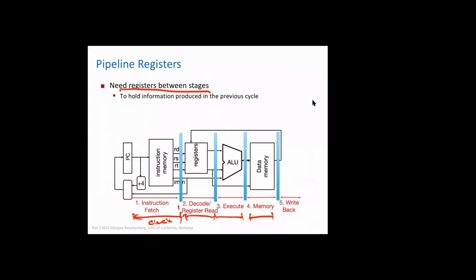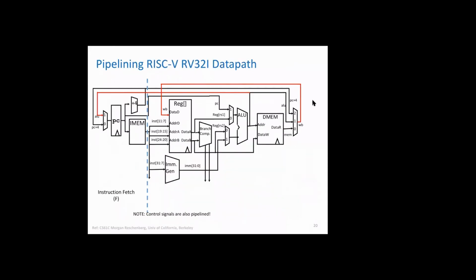Now the thinking is, why do we do that? Because if you design the chip in such a way that these two parts, this header and this thing, are at two ends, then you'll have to carry this signal all the way to the end, and that's not a good design, because it takes some time and so on.